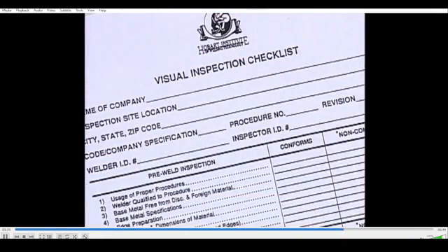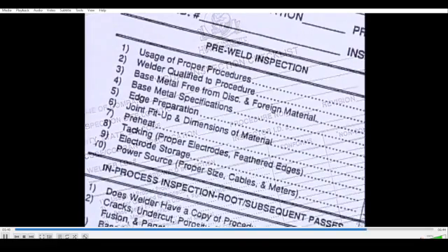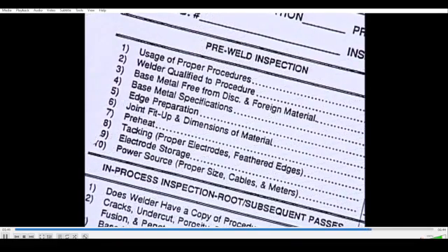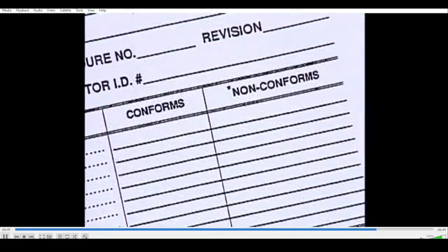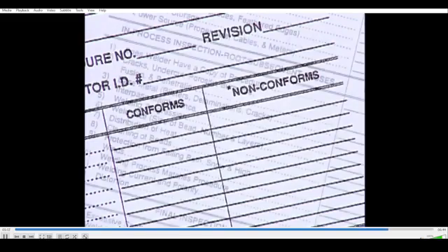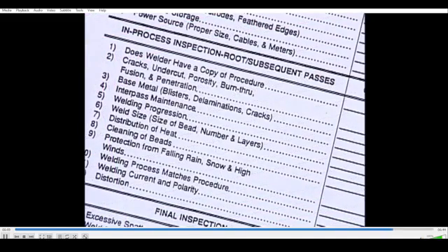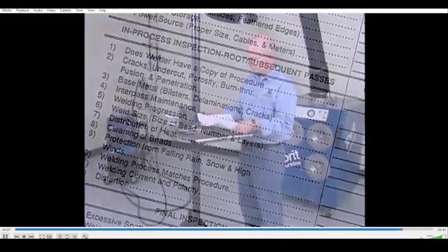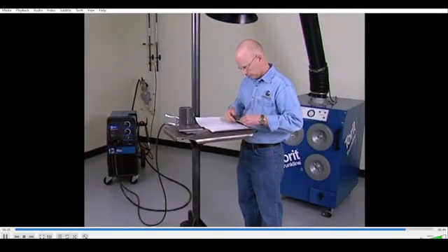Once all aspects of before, during, and after welding inspection have taken place, we must then look at the documentation of visual testing results. The inspector thoroughly and accurately evaluates the results to decide whether or not the welds and weldments meet prescribed specifications. The inspector then makes reports of every detail and keeps complete records. Here, any items which do not meet the requirements are noted and described. If any repairs were made during production, this is also reported. Good record keeping is essential. Whenever such details are required, they are normally signed or certified by the fabricator, with copies made for all personnel involved. Visual testing is an invaluable quality control technique.